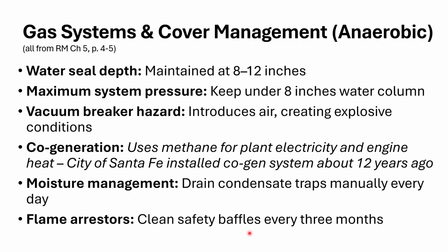Flame arrestors, we want to clean those safety baffles every 3 months. Big deal here, okay? You should remember this. Big safety feature. If we do not clean those safety baffles every 3 months and we have blockage, we could create an explosive environment because we're not burning off that methane. We're releasing that methane or not having a good burn. We're causing ourselves some problems. So every 3 months, that's got to be cleaned out, the safety baffles on the flame arresters.